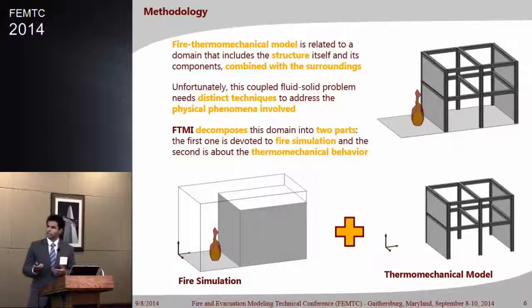So this methodology decomposes this domain into two parts. The first domain is devoted to fire simulation, where all the structure is simplified, and we include the surroundings where we have the flame and hot gas dynamics. The second domain is related to the thermomechanical behavior, where we just have the structure. So to create a bridge between these two universes, we need to characterize the thermal exposure of the surface and create a boundary condition for the thermomechanical model. That's what we're trying to do here.